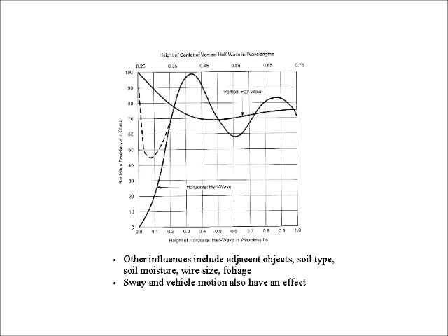One of the reasons. The Earth has a profound effect on antennas. By the way, what else affects antennas? The sun? Well, that actually affects propagation because of the ionosphere, but foliage affects antennas. Other material around an antenna, especially metal, affects antennas. Everything around an antenna affects an antenna. If it rains, the conductivity of the Earth changes, and it changes the characteristics of your antenna. It may not change it much, but it changes it, yes.